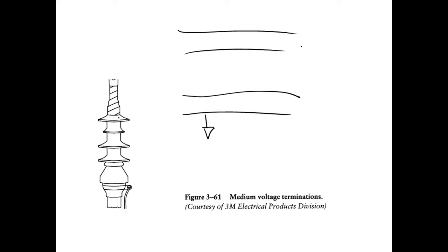We don't use ground. So what we do, I'm going to put digital because it's a little easier to understand. I'm going to send a digital signal. We have one conductor which uses this symbol right here. What we've got to understand is this is a symbol, and a symbol is what we use to represent things. So in differential signaling, the plus symbol means this is the uninverted signal. And on the other wire, which they label minus, they send the exact signal, but they send it 180 degrees out of phase.